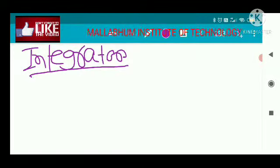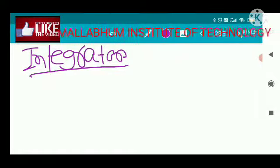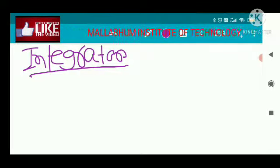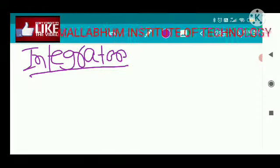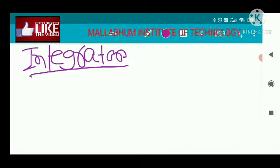The integrator circuit is nothing but your inverting amplifier, where the feedback resistance RF is replaced by a capacitor. That's it. If you replace the feedback resistance RF in an inverting amplifier with a capacitor, then the integrator circuit is generated. So I am just drawing the circuit.